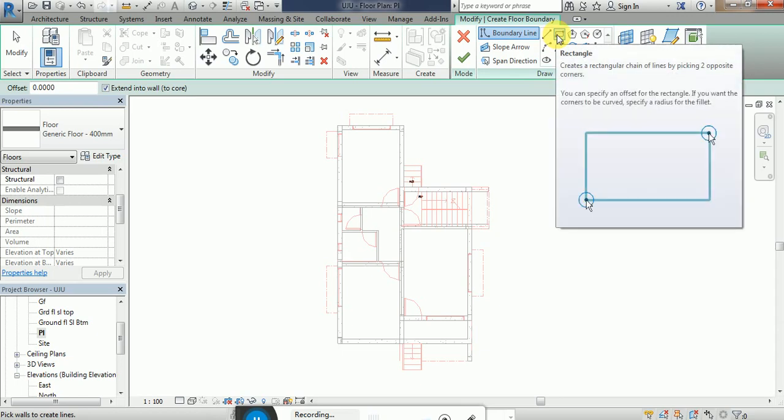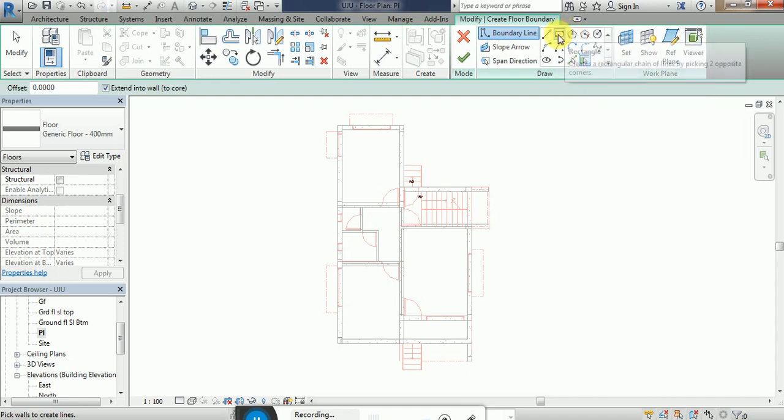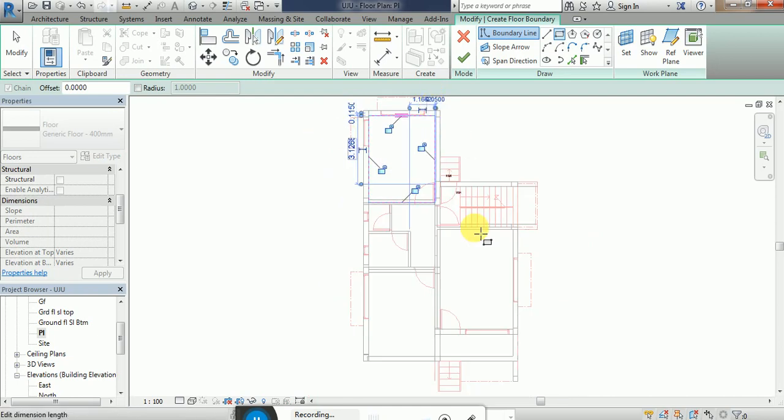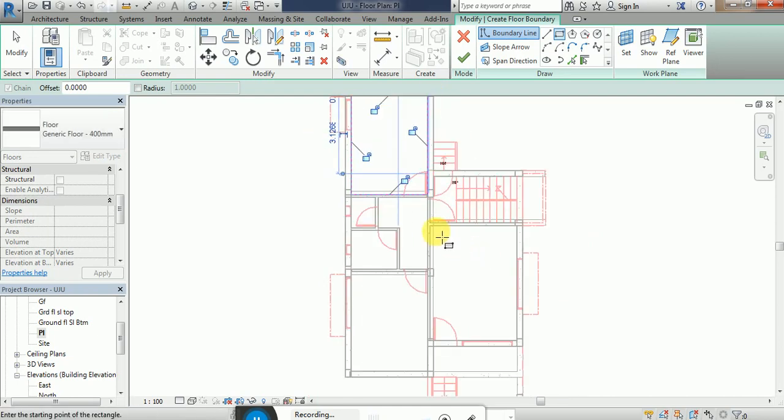Floor will include the mass concrete, meaning bed concrete, as well as some mortar and granite or tiles above that. So that will be the total floor. So I can use the floor command like using a rectangle within the rooms, because flooring will be within the rooms. So this is nothing but the floor using the floor command, the architectural command.